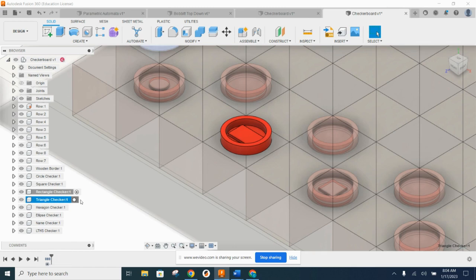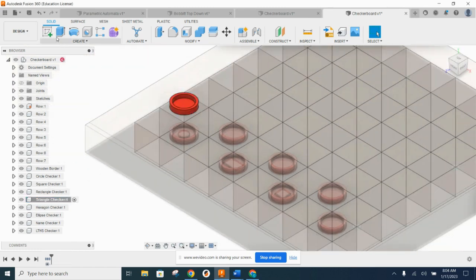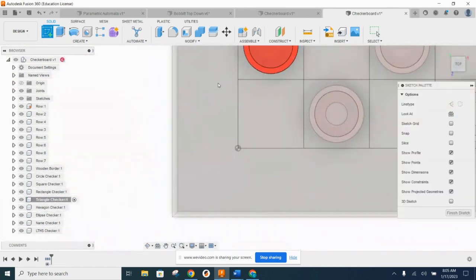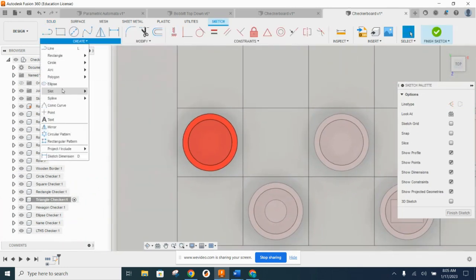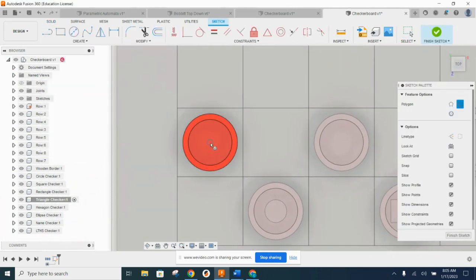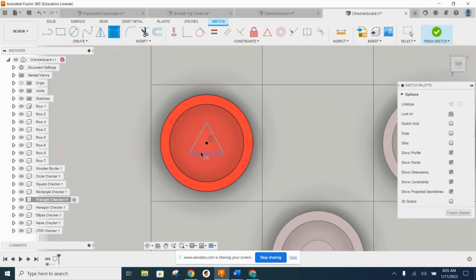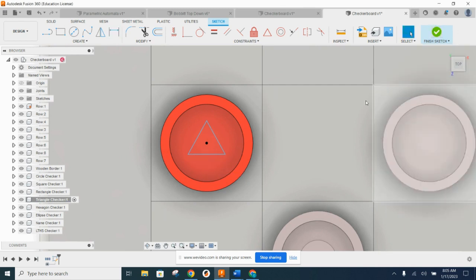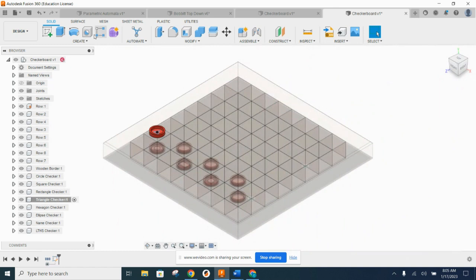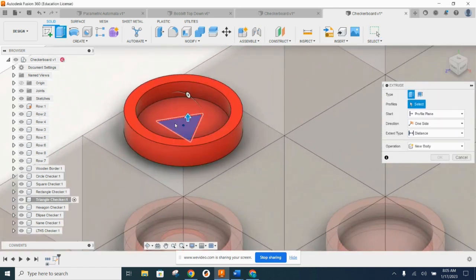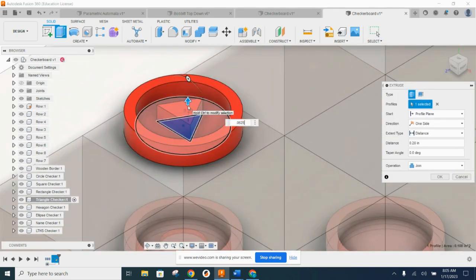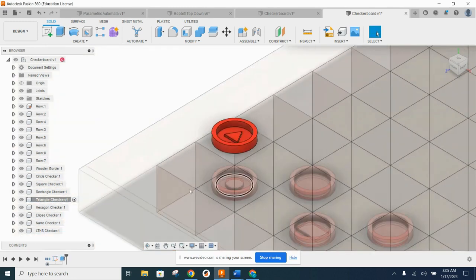Moving on to our next one, we're gonna go to triangle. So let's create a sketch, go right there to the base. I come up here, I can find my polygon. Go to a dead center here and switch this to a 3-sider, making this triangle. Now I can go ahead and put that in place. And I'm gonna go ahead and just put a dimension on this one of 0.5. All right, puts that right in, finish the sketch. Go up here to my isometric view. Let's do an extrude. Pull this up, 0.0625 once again for my thickness. Okay, and that one is done.